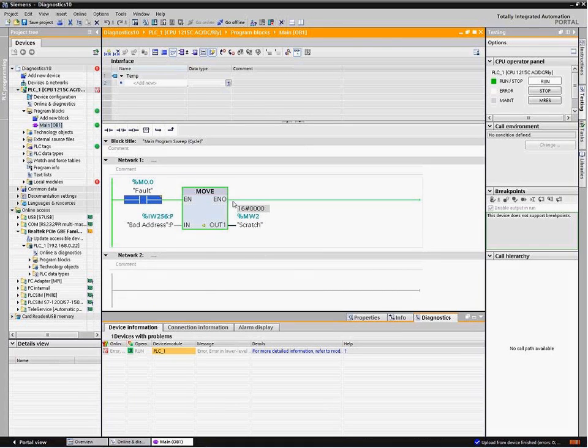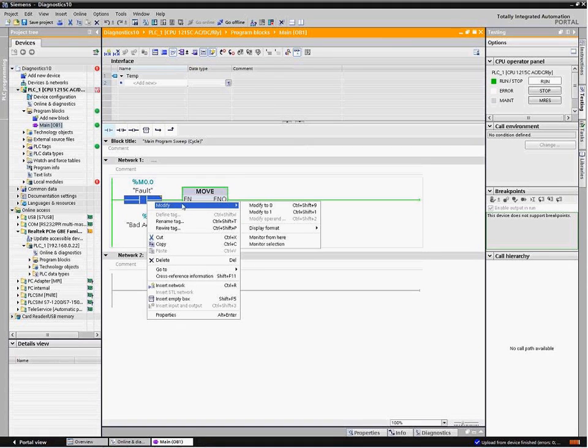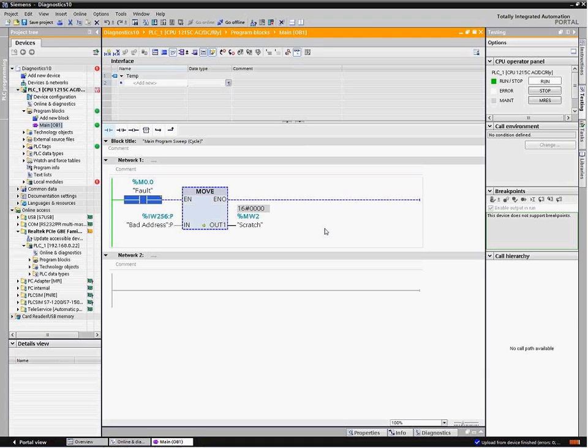I've gone ahead and turned it on. We start seeing red lights all over the place. We have an error. So right now, these are the lights on the front of the PLC, and this would be showing a flashing light. So during the instance where this problem is actually happening, we have diagnostics showing up on the PLC, so someone out there on the plant floor could see a flashing red light and know that there's an error. However, with intermittents, they just come and go. So now we'll just go ahead and turn that off.